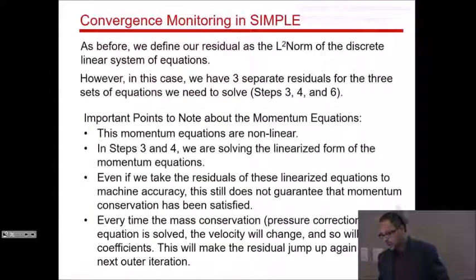So, important points to note about the momentum equations: they are nonlinear. Okay, in steps 3 and 4, we are solving the linearized form of the momentum equations. Okay, and even if we take the linearized form to machine accuracy, that still does not guarantee that momentum conservation has been satisfied. All right. Every time the mass conservation equation is solved, velocity will change, and that will automatically violate momentum conservation again. All right, so you have to do all of this simultaneously, and the residuals will jump back.